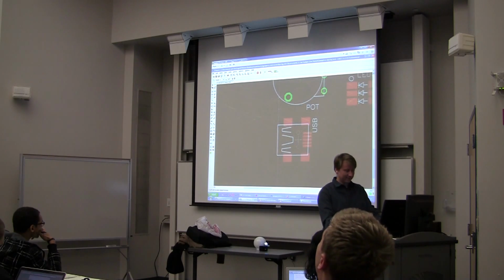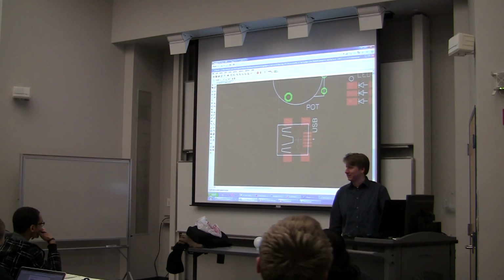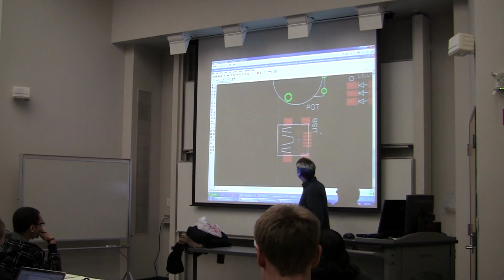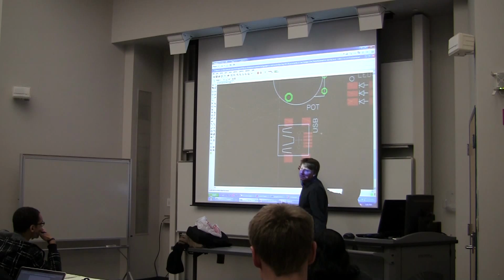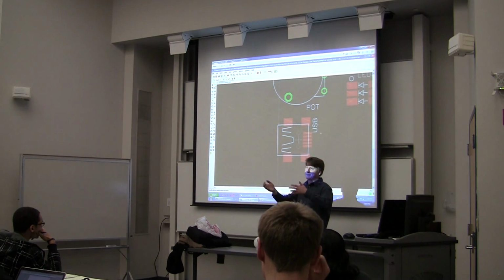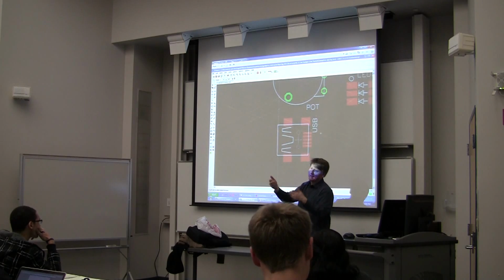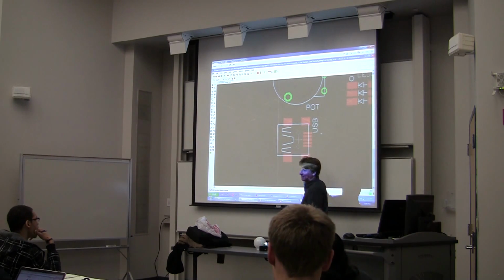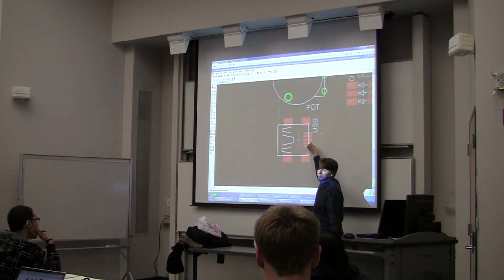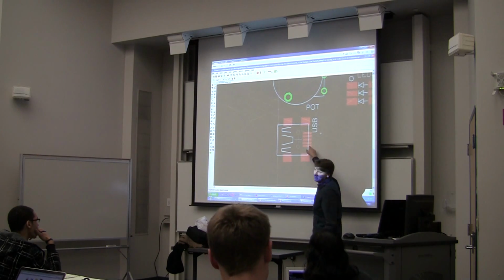No, this is where your legs solder. So this is one of the most common things: here's this drawing. You just trust us that it's the right drawing. If you never go to the data sheet and see where they have the 3D model of the part and how it corresponds to this thing, you might just say, oh, that's where all the pokey bits are. Surely that's where I plug my connector in. But no, that's actually the legs on the back of the part.